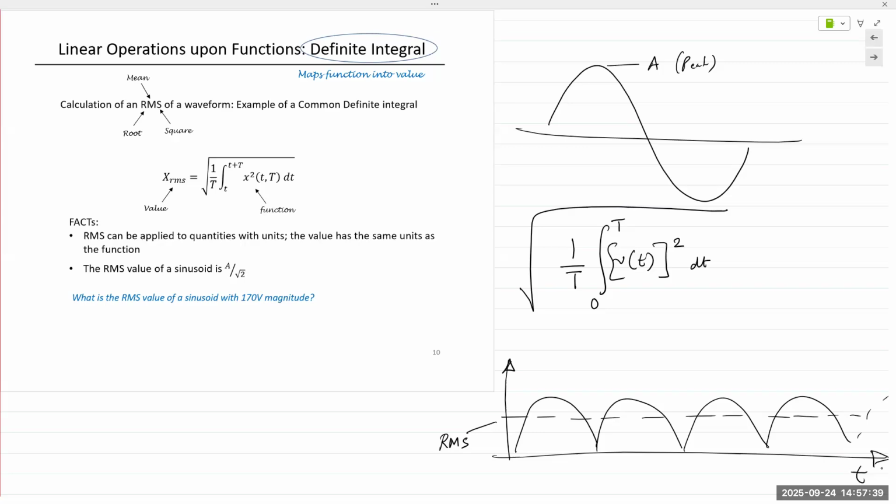Anything that you measure in the lab with a meter, with a benchtop meter, or even a handheld meter, is always RMS because it's providing you one single value. Any meter measurement is always RMS. DC doesn't matter. DC is always constant, so there's no RMS value for a DC. DC value is just the DC value. But for AC, the RMS value is one single number.